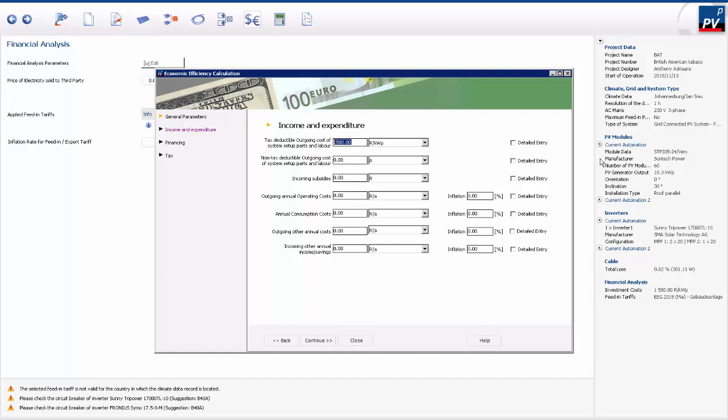So if you work on 20 rand a watt, that's what I want to do. 120 times 335 times, I work on 20 rand a watt, 732,000, right? But is that not for 2 inverters? What do you mean? Well, we've used the 17 Sunny Tri-Power. I used the 2 inverters here, so it's a system size, 34 kilowatt. Yeah, that's what I did. 34 kilowatt, multiplied by 2. But, okay, I said the modules. Okay, so I can say the rand value, right? And the rand value is 732,000, right?